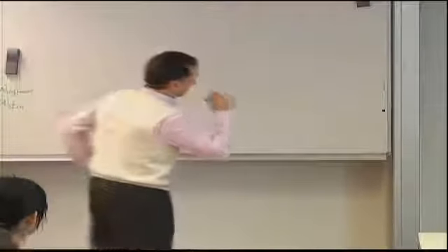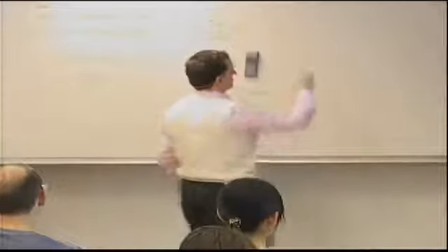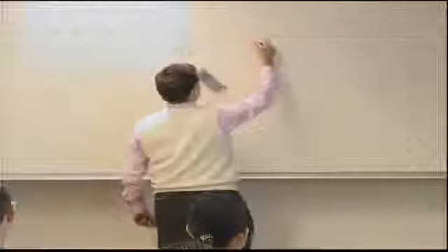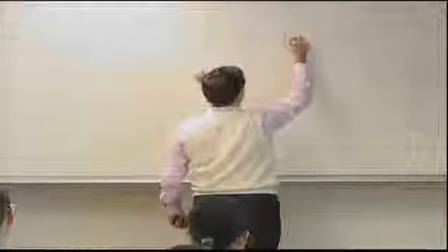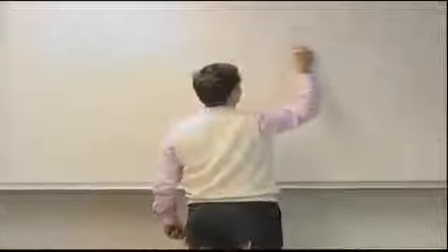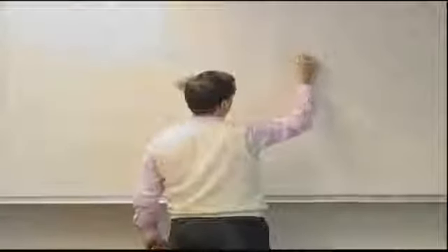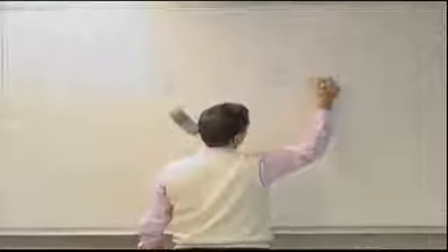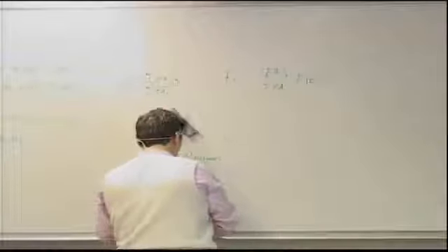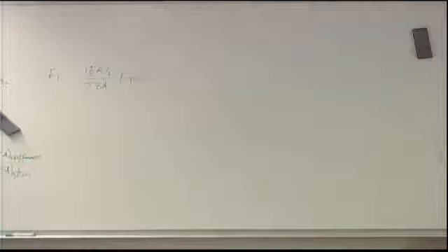Knowing the EA, I can calculate how much of the total force is on the ith member. Remember our equation that Fi is the EA of member i divided by the summation of the EAs times the total force. That's what we had said before.